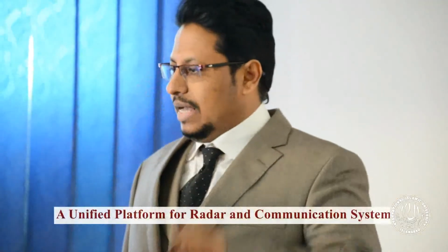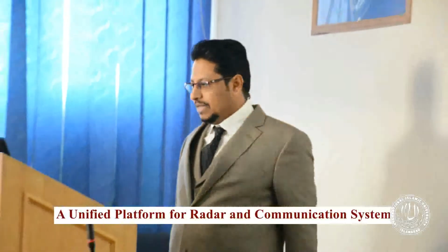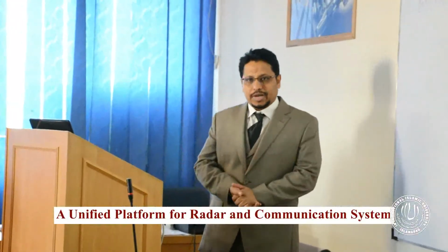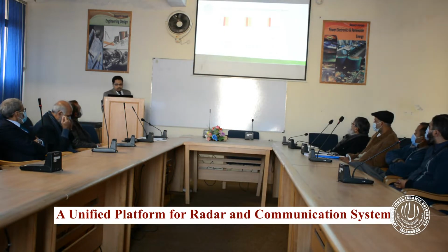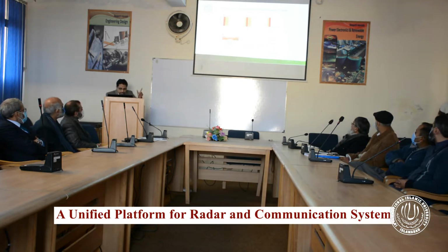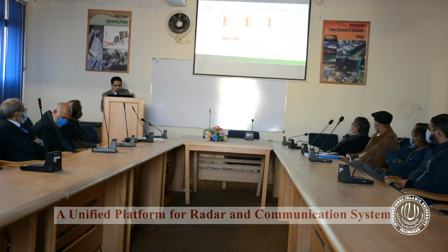Other people use index modulations like code shift keying, in which each waveform is considered as a code representing a bit, so it can be transmitted normally with radar emissions. Others use frequency hopping, enabling the frequency hopping to be transmitted with the MIMO to carry information. Others use FSK, and this was our contribution, in which we use two orthogonal frequencies, where each frequency represents a bit of information. So we will see it later on.